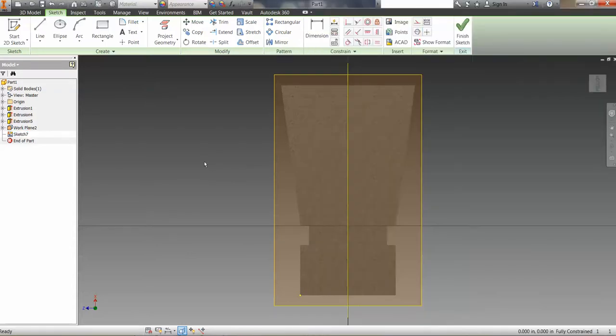I'm going to go ahead and create my shape, knowing that I want this sort of trapezoid with an arc on it. So I'm going to use the line command, and I'm going to come down here, and I know that I want to be on the corner of my shape, so I click the corner of my shape, and I'm going to drag a diagonal line out at an angle away from my shape.